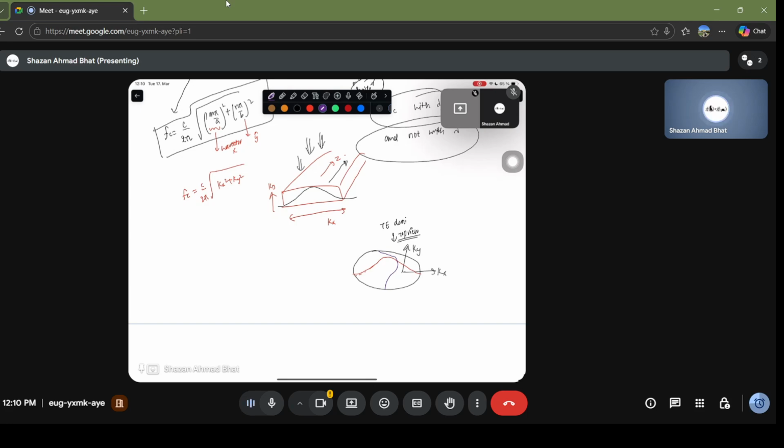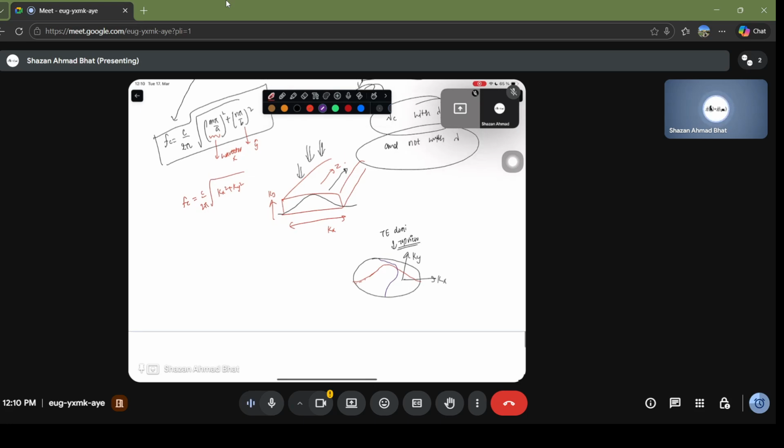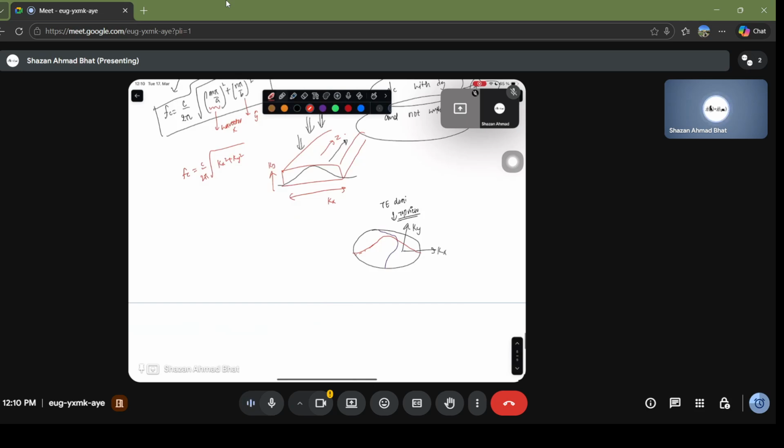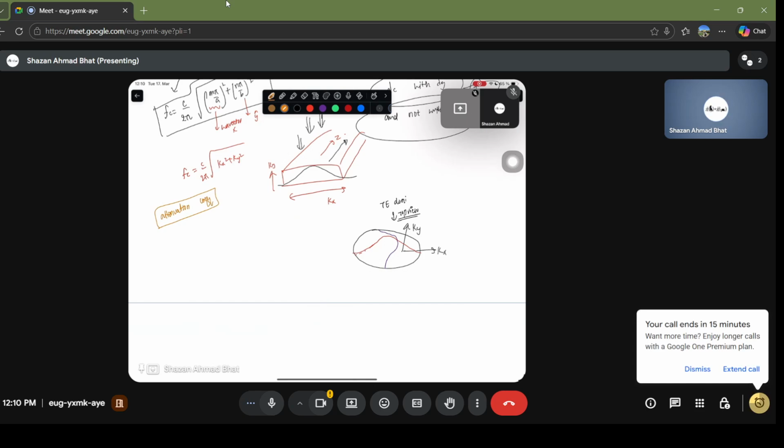Okay, so again we talked about intrinsic impedance, the impedance inside the waveguide for the dominant mode. We again talked about the attenuation coefficient for this dominant mode inside the waveguide. It will again be modified by this particular term, which is the square root of fc divided by f, squared, minus 1.